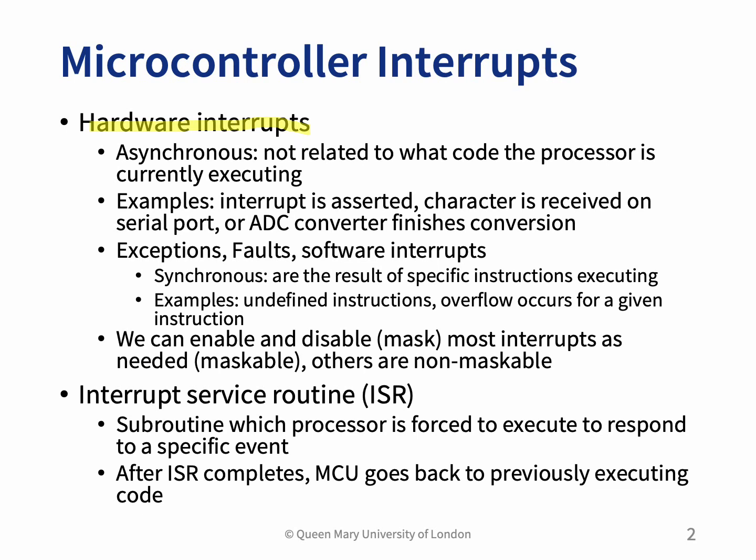In terms of the hardware interrupt, the behavior is asynchronous. It is because it is not related to what code the processor is currently executing. A hardware interrupt is where the interrupt signal is sent to the processor from an external device.